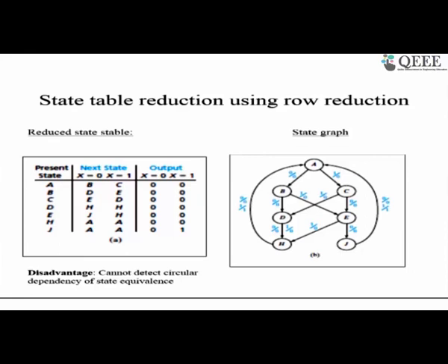Why are we using flip flops in the feedback of an FSM? As I mentioned, finite state machines are the machines which remember the state of the circuit and respond differently at different states. So it has to remember the history of the input sequence. So we need memory to remember the history, and therefore we need flip flops to store it.